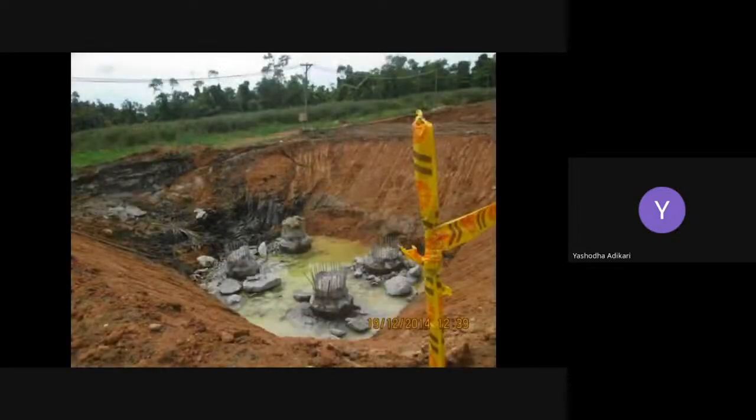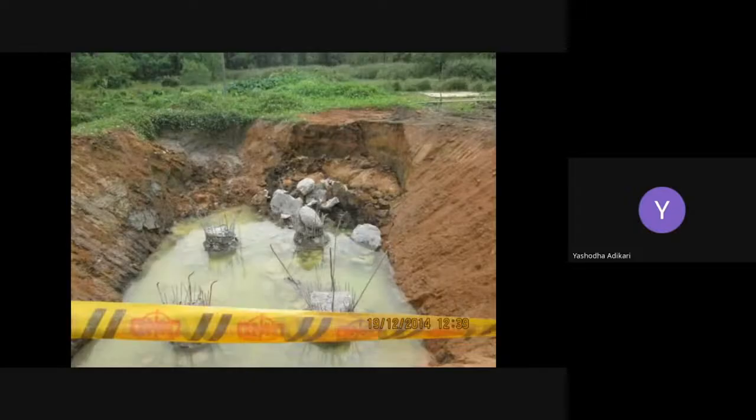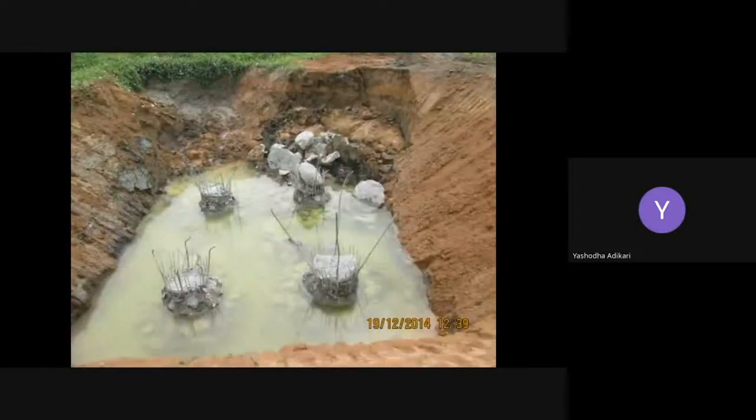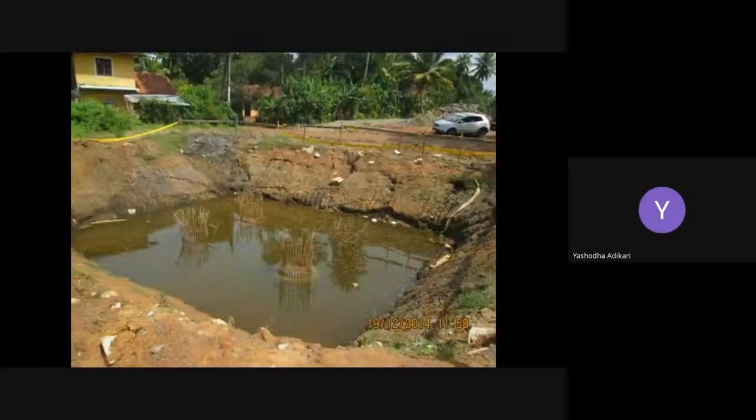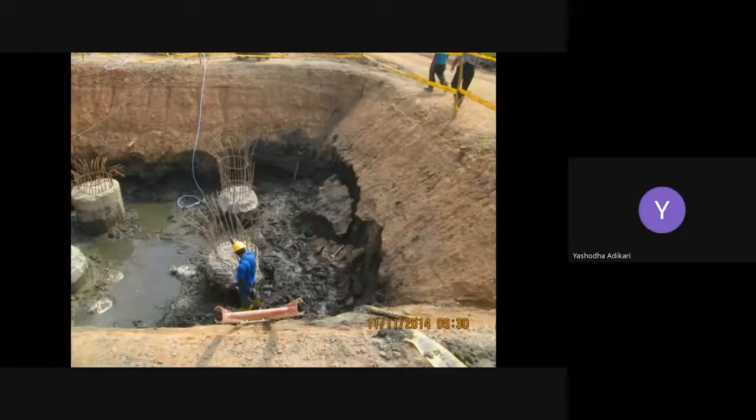The contractor's initial plan was to carry out excavations maintaining stable cut slopes. 1 to 1.5 cut slopes are usually stable on firm ground. In this site, the water table was high and the ground was unstable. With time, the cut slopes started to fail, halting construction works.